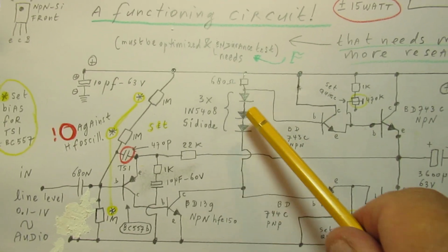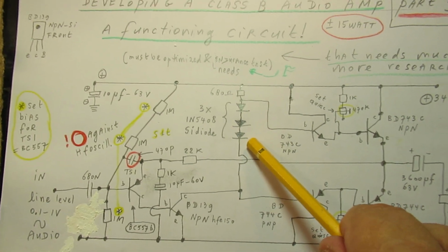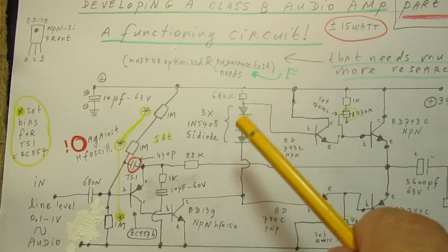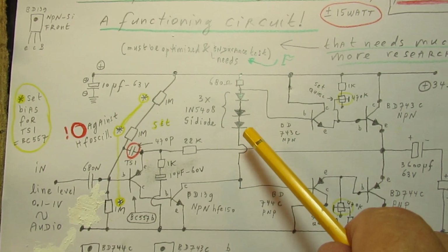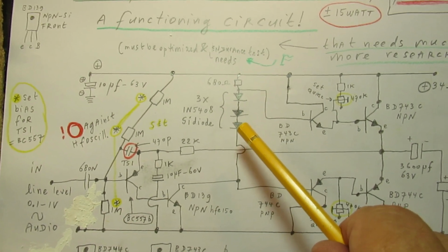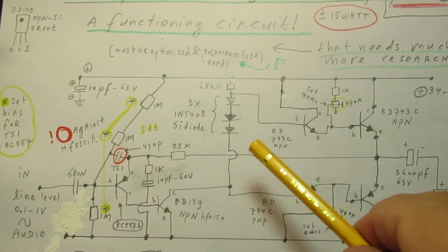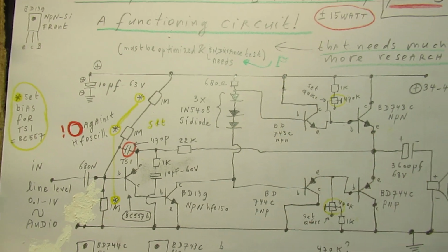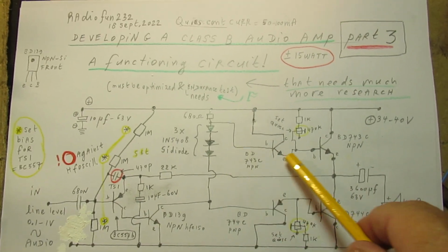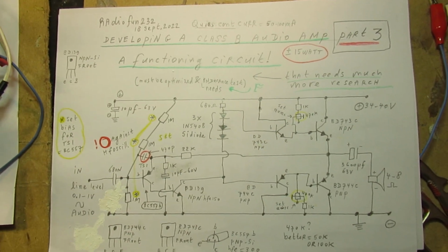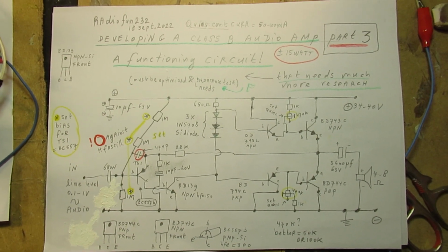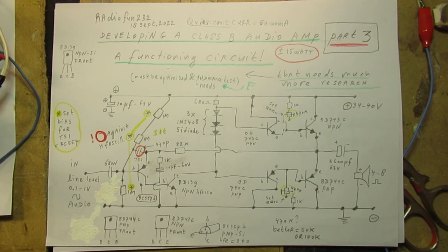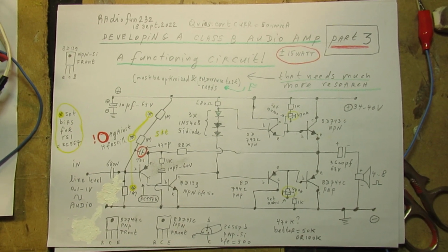That means that we need here 3 diodes. You can try 4 diodes. You will surely see that immediately the quiescent current goes very high. And with one diode less in that row, you hear distortion. The transistors are not driven out properly. I will say stand still now one moment by that schematic.